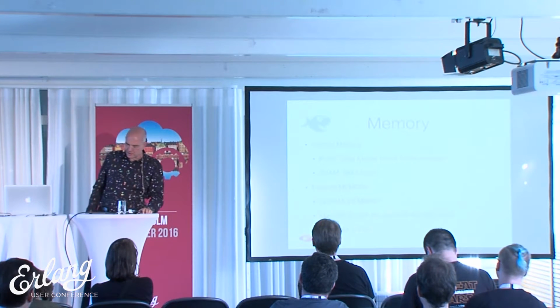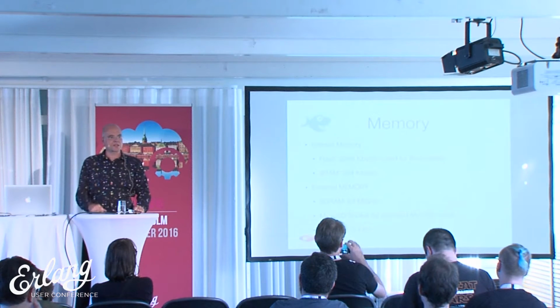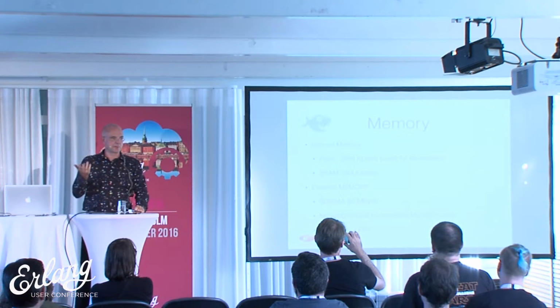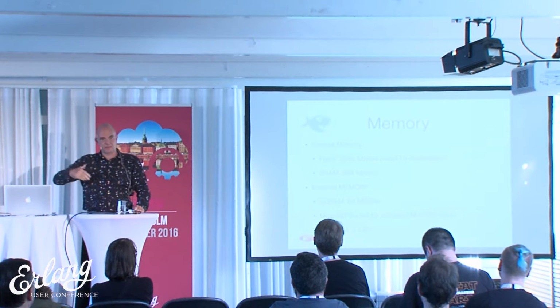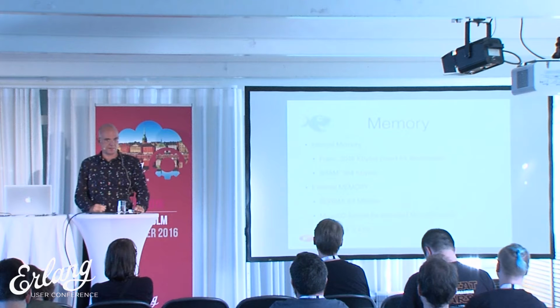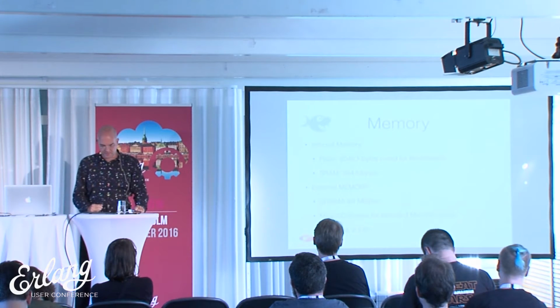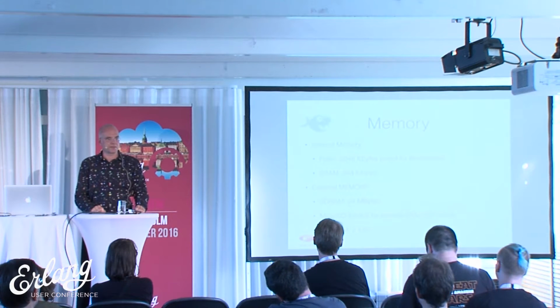You have an FPU, and the memory, as I mentioned, there's an internal flash which is only used for the bootloader. The little program, which incidentally is also RTEMS. So RTEMS is the bootloader and is used for running the Erlang VM at the same time, because it's so small that you can build a very small bootloader with it. Actually, you don't need most of these 2 megabytes. And there's the SRAM I mentioned and the other RAM. There's also an EEPROM where you can store configuration data or stuff like this.